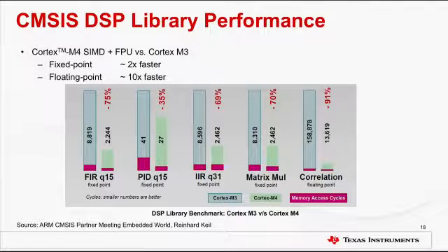For details on function descriptions, return type, arguments, and examples, please refer to the CMSIS DSP library documentation made available by ARM. The CMSIS DSP library is completely written in C, builds and runs on the Cortex M4, M3, and Cortex M0 processors. Maximum use of Cortex M4F intrinsics allows for high performance in Cortex M4 based devices. The DSP library performs about 2 times faster on Cortex M4 in comparison with Cortex M3. It also performs about 10 times faster on Cortex M4 with floating point in comparison with Cortex M3.